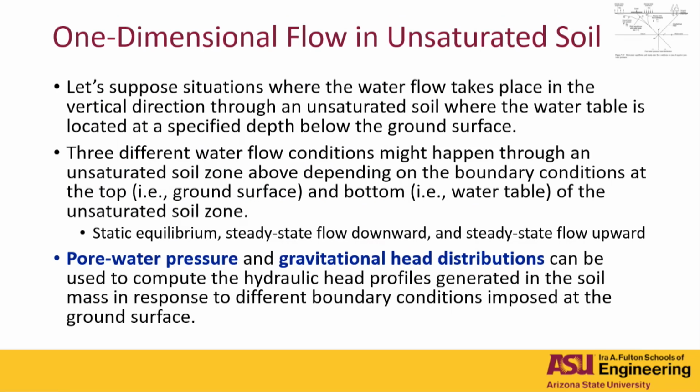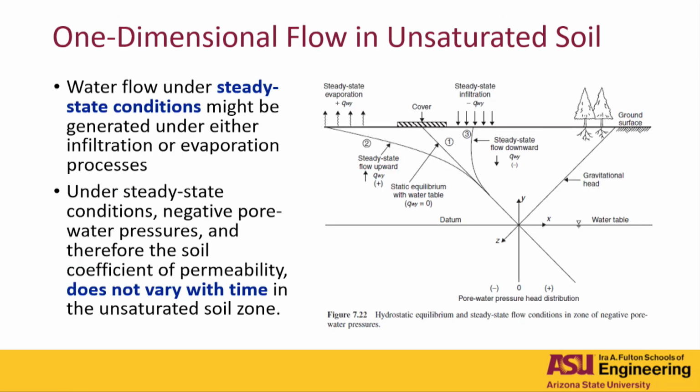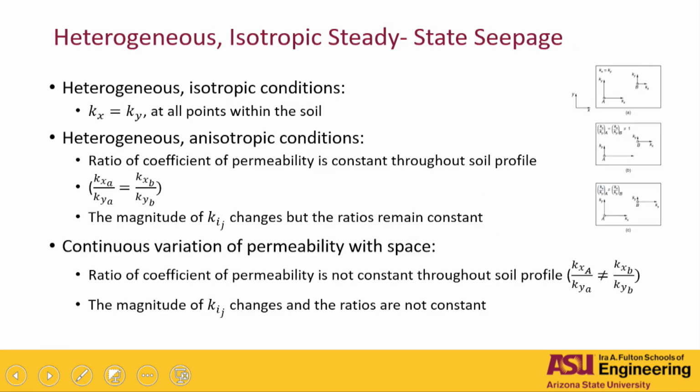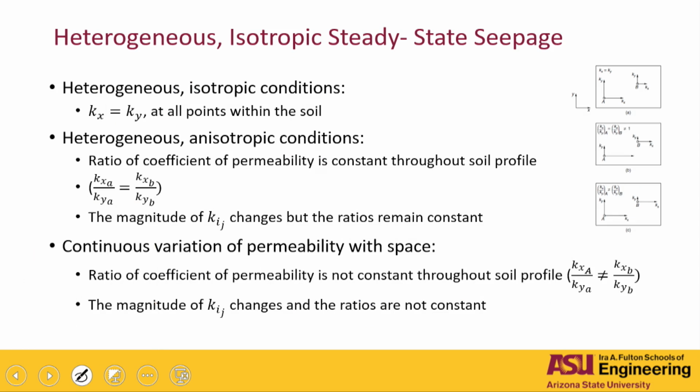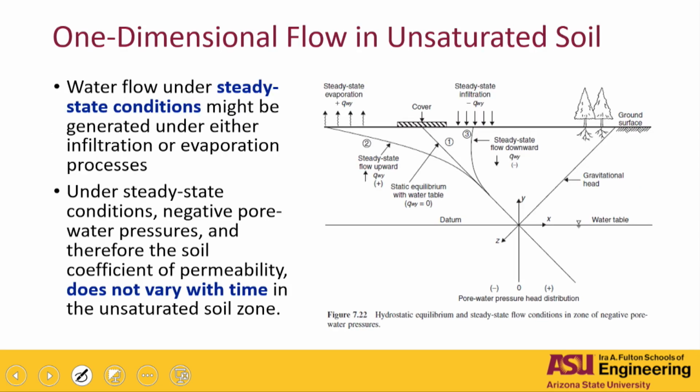We assume that the pore water pressure, the suction is... We assume that the pore air pressure, again, just keeping that in mind, is equal to your suction, right? So I'm talking about the line that you saw here, the line that you saw here is the negative pore water pressure, right? So if you assume that the pore air pressure here is atmospheric, you can assume that to be 0. That's basically your suction value, right? Going up is your steady state equilibrium condition.